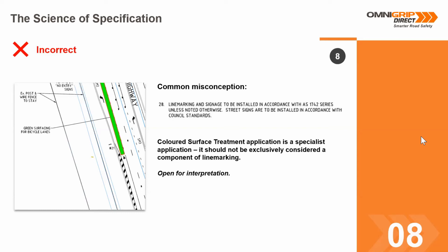And depending on traffic, the paint will fade away, and the quartz or sand that's potentially been placed in the product to give it a little bit of friction will disappear, and all you have is paint. And when the road surface is wet, guess what happens on paint? It becomes very slippery and unsafe. So instead of making the road surface safer, this product makes the road surface a slip hazard, and it's probably the last thing anyone wants.